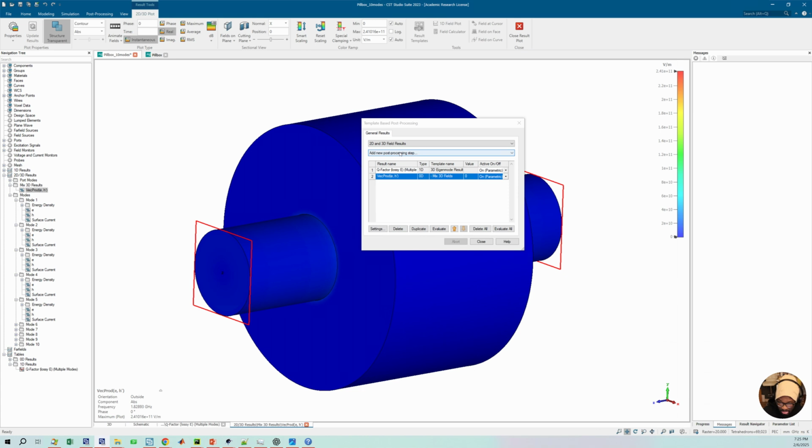For a final mesh, I would expect the power flow from the two ports to converge, but I did not check, because this one for some reason took a lot of time to run. Probably it's because of the frequency range I was considering, though the number of tetrahedrons wasn't big. I didn't have much time or patience to look at why it was taking so long, so I just let it run and did some other things, and that worked for me.